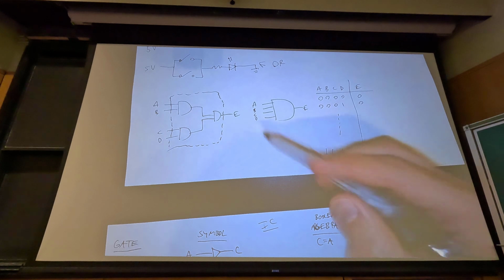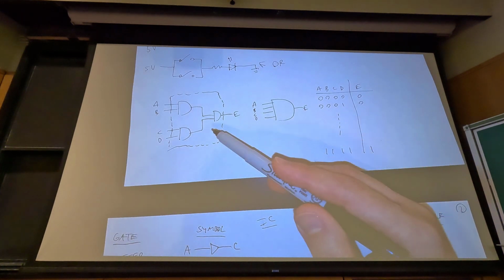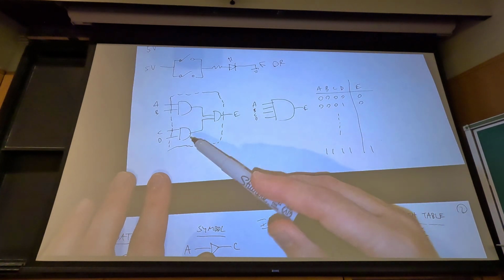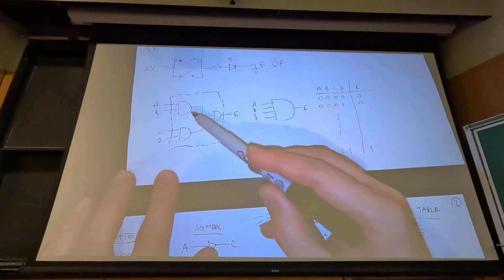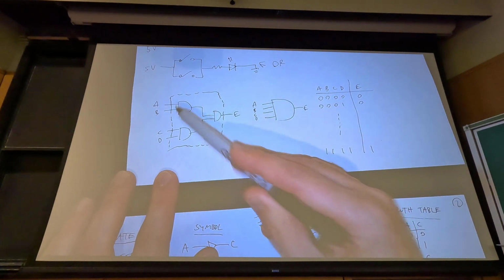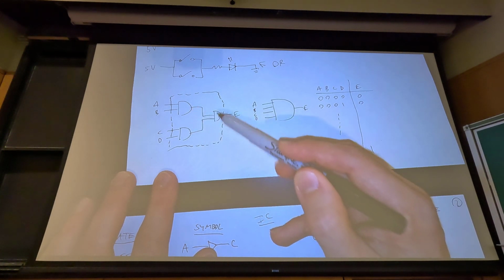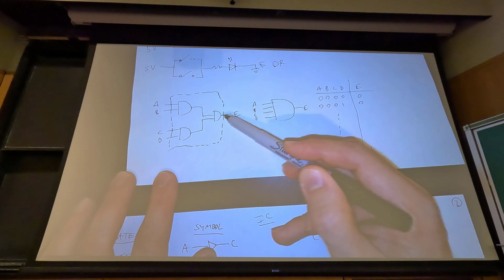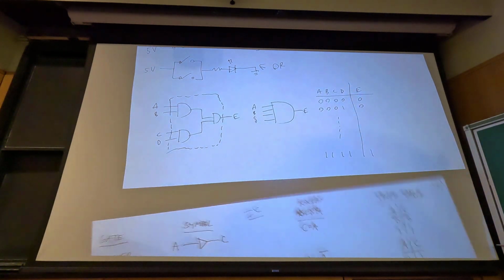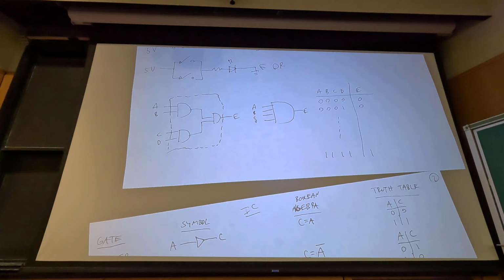So I just demonstrated that with AND gates, but what I was asking you to do in Tinkercad is to do this with individual OR gates. You have your 2 inputs going to 2 different OR gates, and then you chain the outputs of those 2 OR gates to the inputs of the final one, and the final one is what controls your LED. Okay, so if I switch back to Tinkercad,